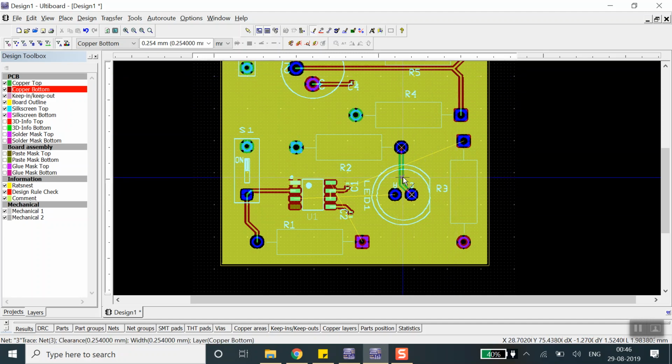So the clearance over here is the blue and the clearance over here is the red, because these are on the top side and this is on the bottom side. So all these components except this one, which is a 555 timer, are through hole components. So basically there's going to be a hole in the PCB on this part. So these components are easier to connect on any layer. You can connect this from here to here on the top layer or the bottom layer, because it doesn't matter, the hole is there.